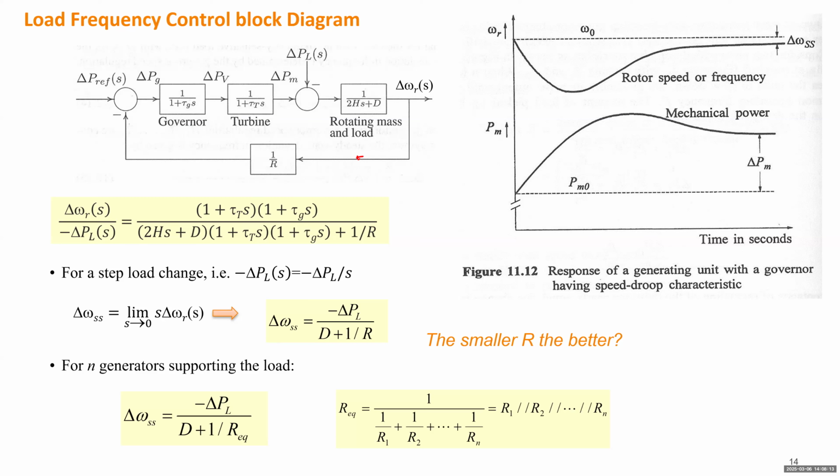It is like this, if you're familiar with such a component. When the speed deviation goes through this component, it needs to follow this curve. And this H will be maybe 30 millihertz. So within 30 millihertz, it doesn't change at all. Only when beyond 30 millihertz can it start to change and influence this one.